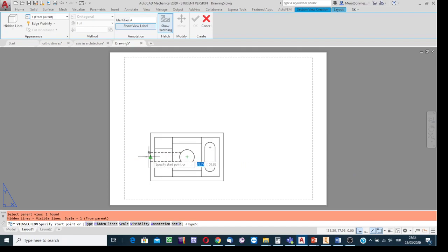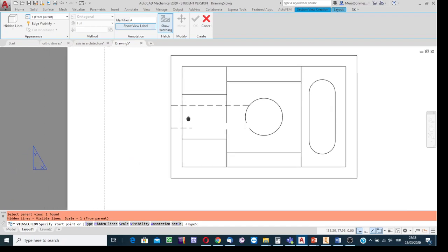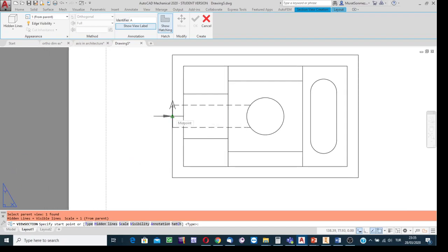So you see, after bringing the cursor to the vicinity of a snappable point, it can snap. Move the cursor away, and I can see on the screen such a track line. It appears as the line passing through the cursor and the characteristic point. We can have such useful lines to follow by keeping the object snap tracking button on the status bar in on status.